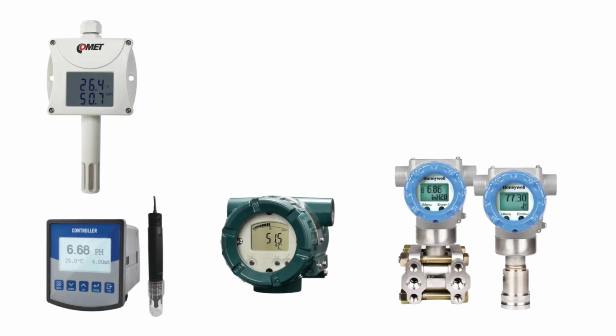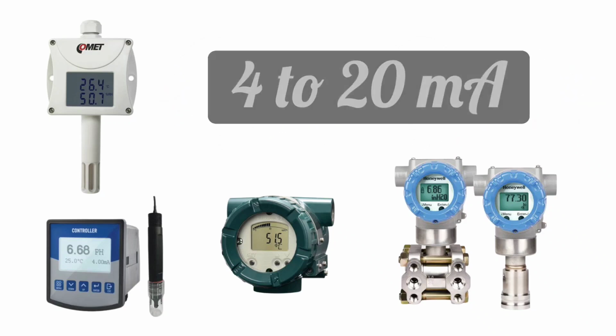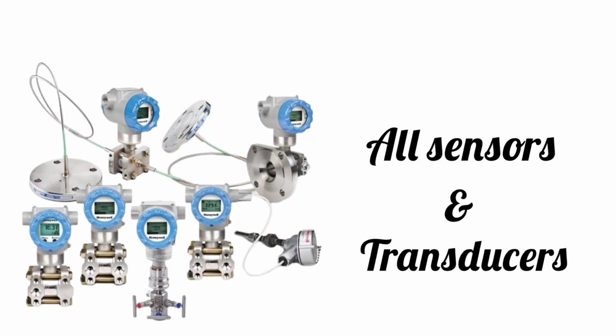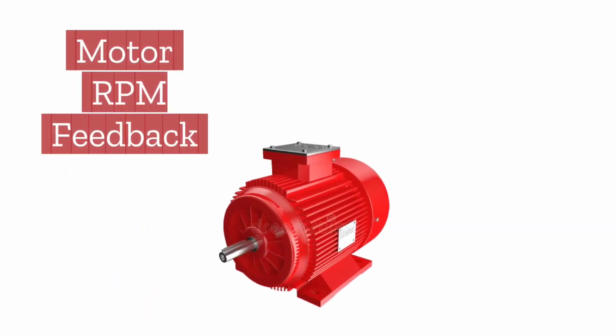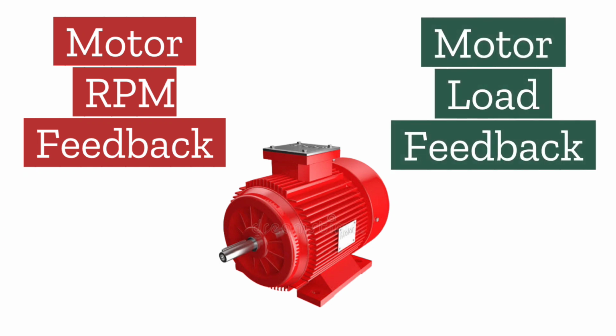The output value of all these transmitters also varies in a range. The output of all these transmitters is usually 4 to 20 milliamperes. In short, usually, the signals of all sensors and transducers are analog input signals. Apart from these, motor RPM feedback, motor load feedback are also analog input signals.